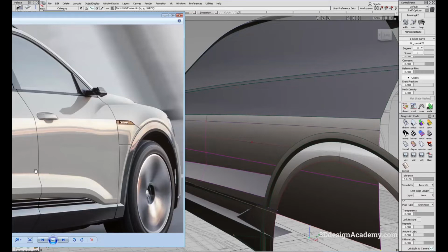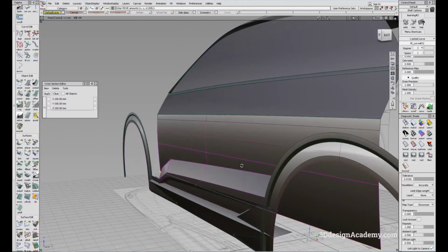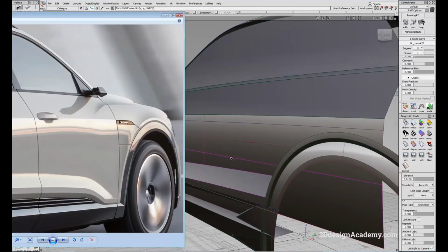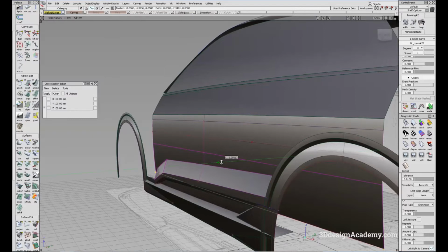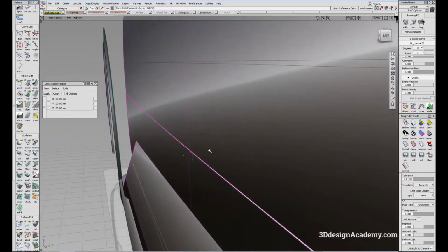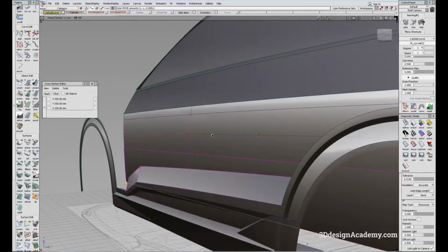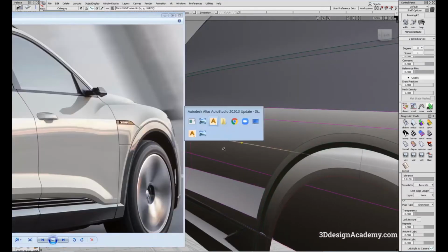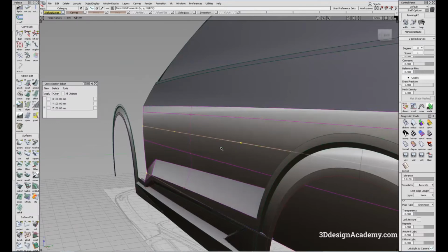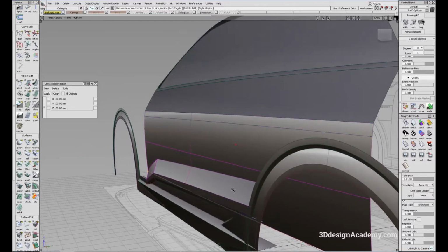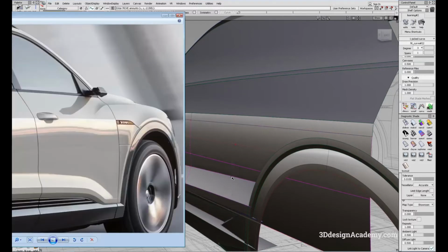If you look at this point and this point, I think it's actually a little bit outboard. At least it feels like it. So I think I need to move it a little bit out. And while I'm doing that, looks like the history is a little bit broken. I'm going to grab this curve and move that out too, because we want to keep the volume similar. Okay, and I'm just going to grab the bottom one like this, and let's compare.